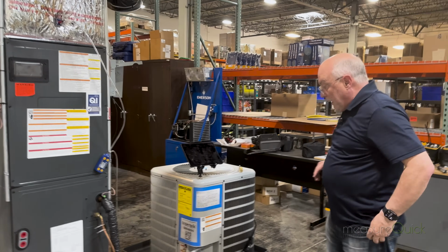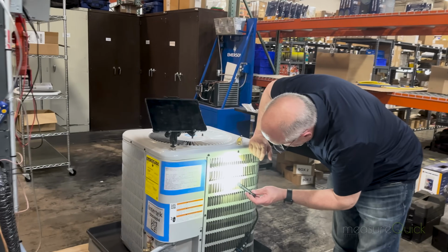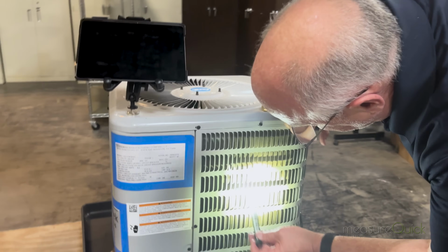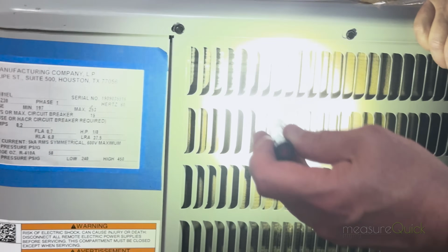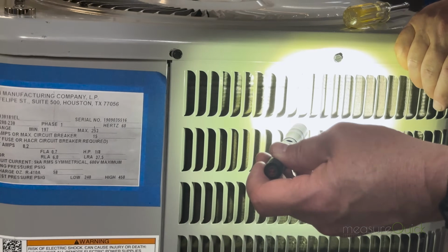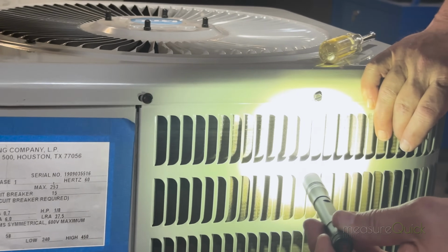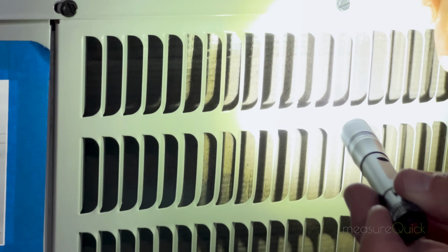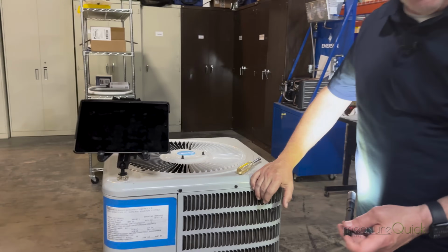Now also we obviously want to do a quick visual inspection of our condenser coil. Which you can see, this condenser coil is a little bit dirty here. So we should probably clean that before we charge the system, right? And it's very hard to see this unless you get in close and actually look for dirt on the coil, but this will actually impact the operation of the equipment. So we'd want to clean this off before we actually do the charging.